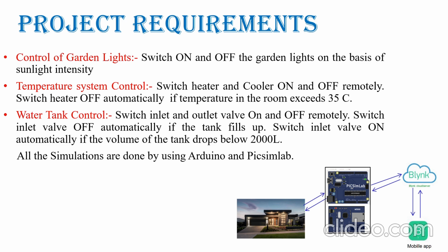Third, water tank control. Switch the inlet and outlet valves on and off remotely. Switch the inlet valve off automatically if the tank fills up. Switch the inlet valve on automatically if the volume of the tank drops below 2000 liters. All the simulations are done by using Arduino and PICSimLab.